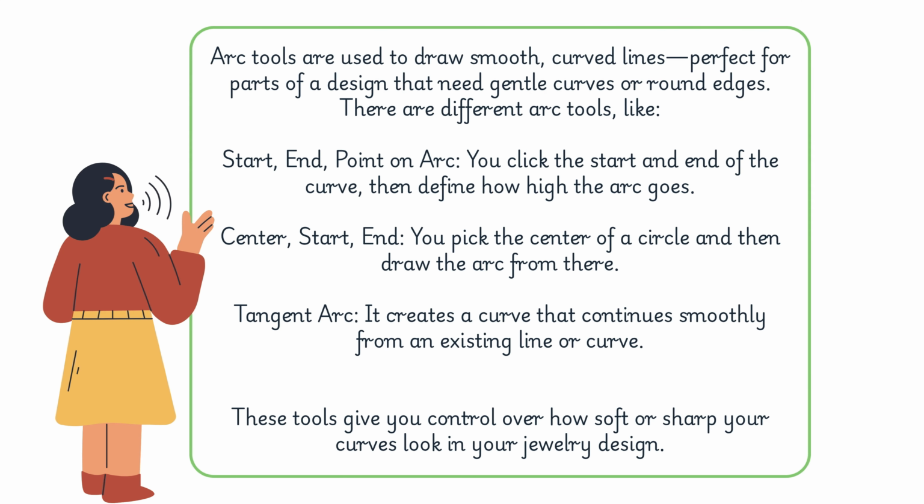Arc tools are used to draw smooth, curved lines, perfect for parts of a design that need gentle curves or round edges. There are different arc tools. Start, End, Point on Arc: you click the start and end of the curve, then define how high the arc goes. Center, Start, End: you pick the center of a circle and then draw the arc from there. Tangent Arc: it creates a curve that continues smoothly from an existing line or curve. These tools give you control over how soft or sharp your curves look in your jewelry design.